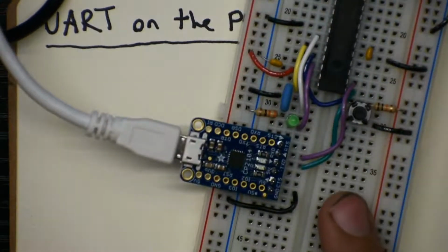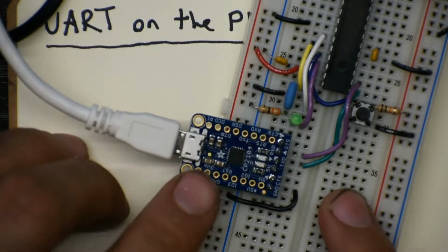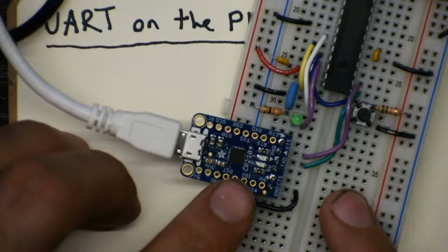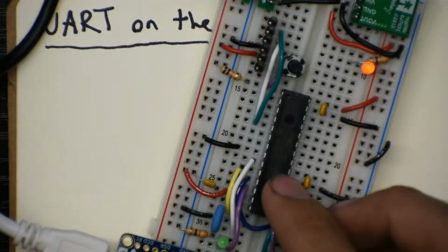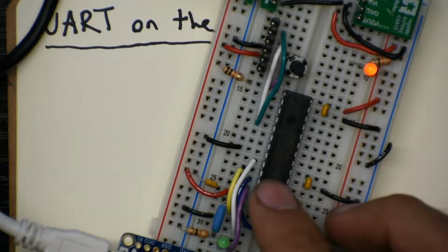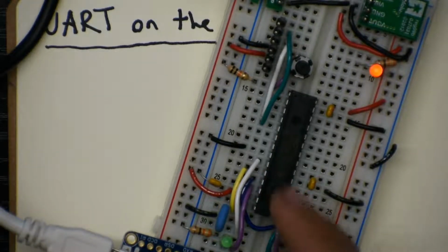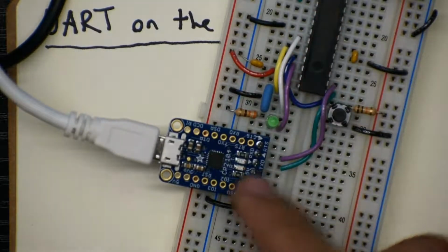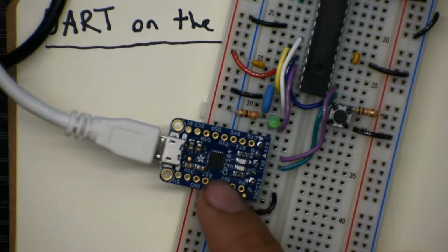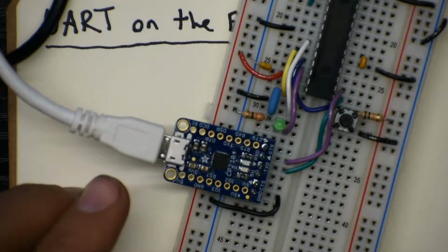And what we're going to do is use this USB to UART adapter from Adafruit. The chip on it is the CP2104 to be able to communicate with our computer. So this particular PIC, the 100 series of the PIC32MX, does not have the ability to talk USB. So the way we can get it to talk to our computer is using UART, and then this chip will convert the UART to a virtual serial port that we can open up in Screen or Putty on our computer.